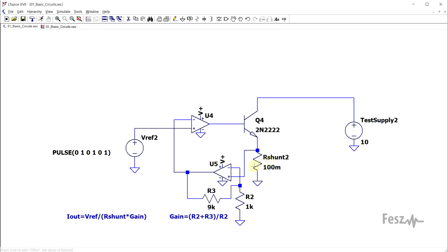If this is a more severe problem though, you can always add in an extra op-amp to amplify the voltage that is present on the shunt. So this allows the usage of either a larger reference voltage or a smaller shunt resistor. But the downside of this method is that this will bring extra phase shift and complexity into the loop. So the strategy is not always advised.